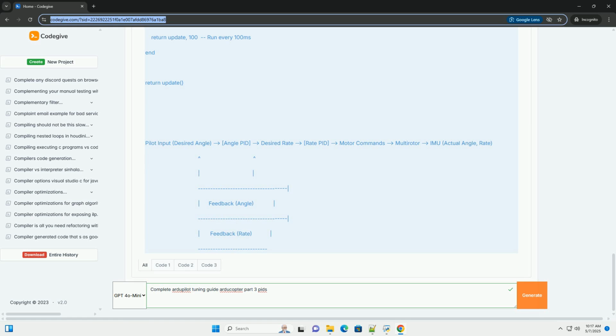Tuning roll/pitch rate PID, iterative approach. These two axes are tuned together, as they are very similar. Focus on rate P first. Increase ATC_RAT_RLL_P and ATC_RAT_PIT_P in small increments, for example 0.02 at a time. After each change, perform a small, for example 20°, quick roll and pitch maneuver. Observe how the multirotor responds.